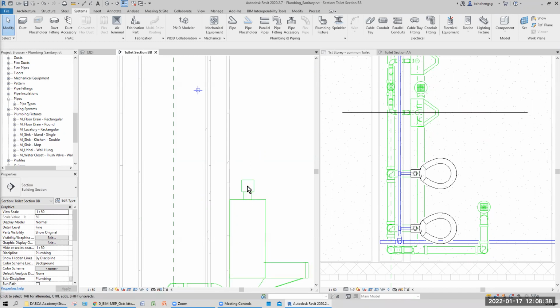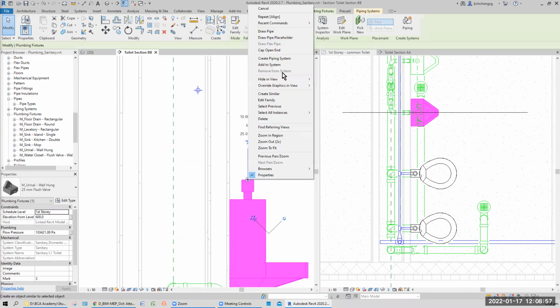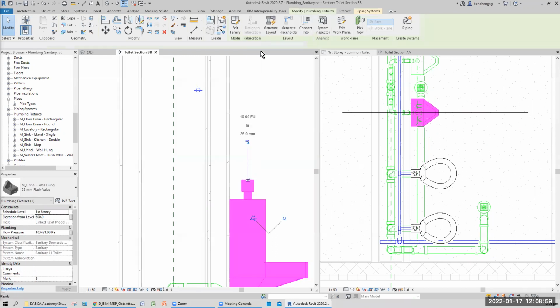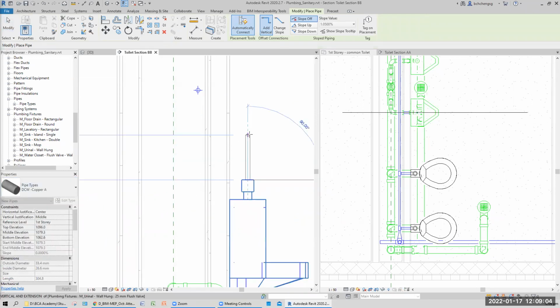That means they must have a pipe connecting here. Turn inside, join here. It cannot be connected too long because people keep pressing. You weaken the structure. The pipe will be bent. Okay, so this part here to draw, select this point, right click, draw pipes, make sure copper. If not, you may want to change this to stainless steel. Stainless steel is still tougher. Copper, you keep pressing, you'll bend later.